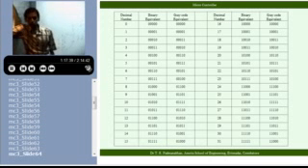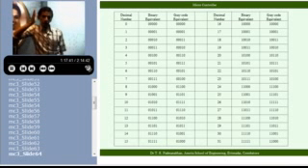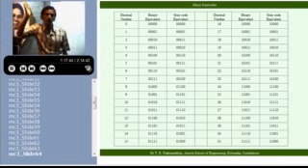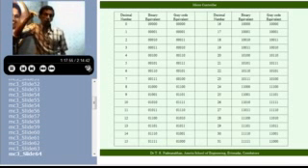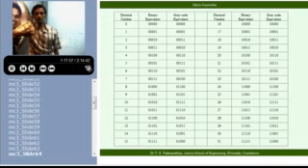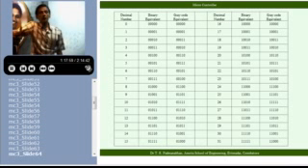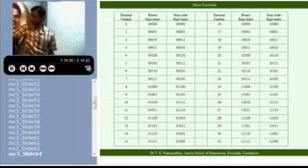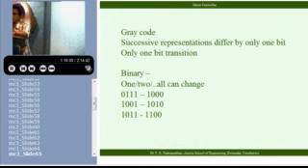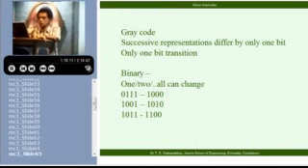Whenever you convert a direct analog position into a corresponding number, a gray code is always preferred. In all transducers, wherever the input is directly converted to a digital number, invariably a gray code is used. So at the input stage, the number is available in gray code, but you would like to get it in binary form. In some cases, you have to convert from binary to gray code. In all such cases, you have to go for an encoder or a decoder.